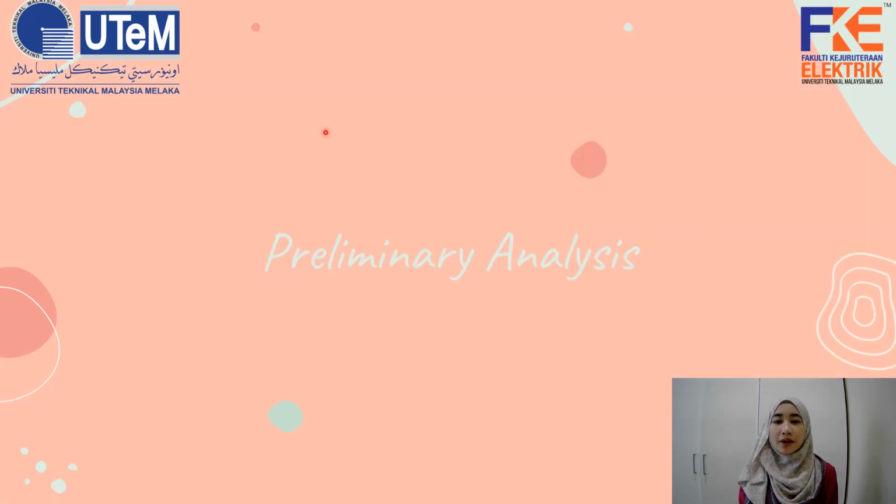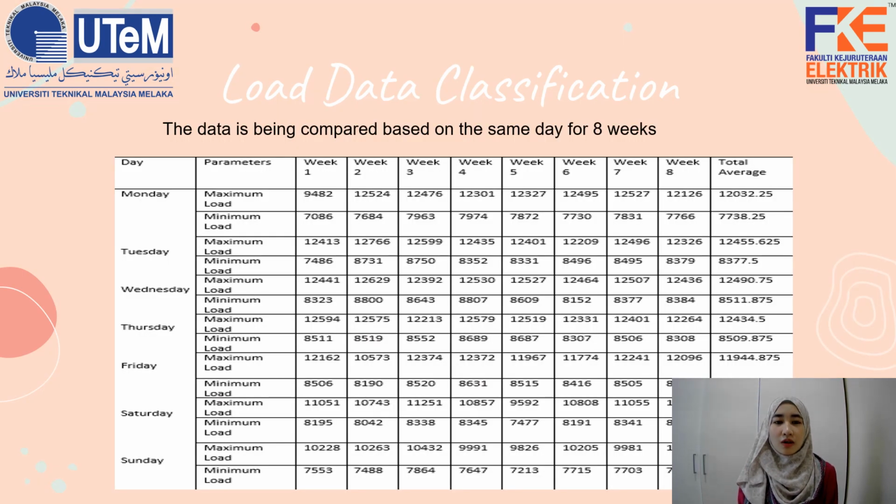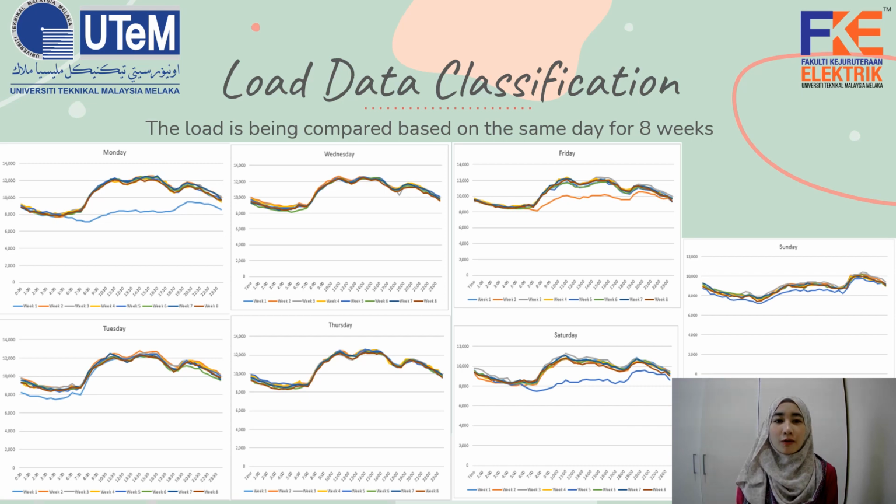Next is preliminary analysis. The collected load data will be classified and compared based on the same day for 8 weeks, which means if Monday, we will compare every Monday data for 8 weeks. We compare the data for the same day because the load data for the same day is almost constant from Monday to Sunday. So it is easier for the LSTM to forecast more accurate data if we use the same day data for 8 weeks.